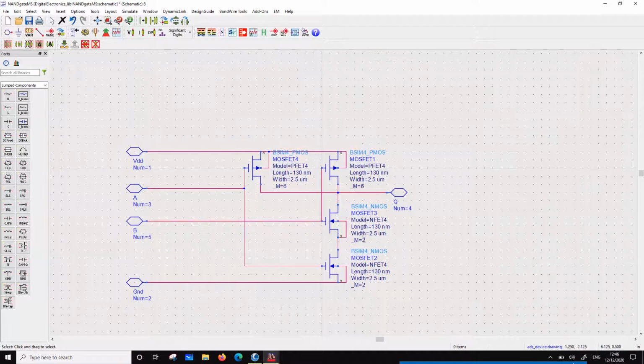The only thing I'm going to do is scale this up slightly. So let's make this 4. Let's make this 4. This is because they are stacked together like this, and these come in parallel. So I can reduce slightly on these. Okay, and this is the configuration which will more or less be symmetric pull up and pull down.